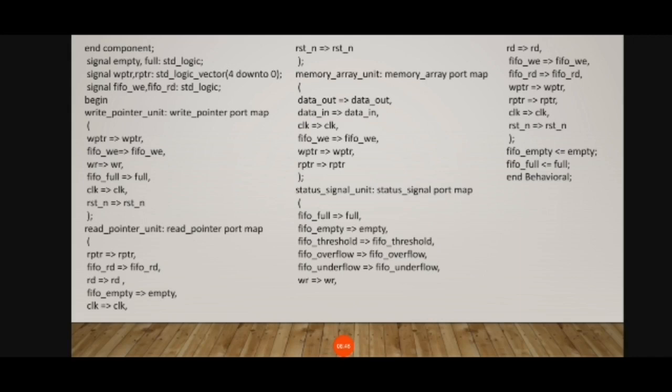FIFO threshold. The FIFO threshold level determines when the data in the FIFO should be transferred to or from memory. There are 4 configurable threshold levels per stream, starting from 1/4 FIFO full to FIFO full. The read port has its associated memory addressing logic called read pointer logic, and the write port has write pointer logic. When FIFO is reset, both read and write pointers point to the first memory location of the FIFO.